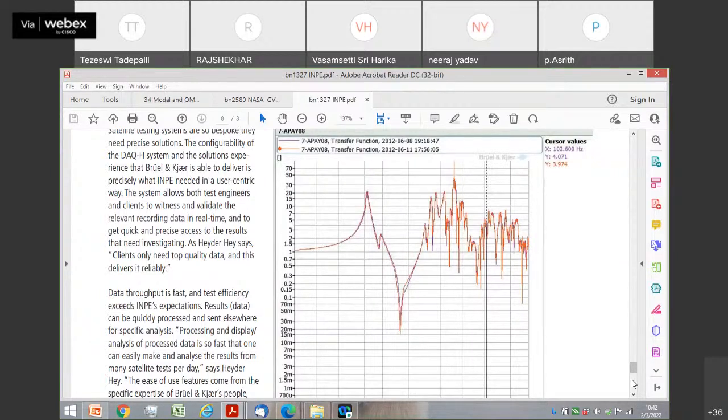Yes, in the coming test we can do that, but the same test we cannot repeat like we did on the cross country roads. So the reason is you have to have redundancy in terms of recording, so that if in one channel you have lost some data, you could look at the second channel and see whether the data is okay or not. That's the only thing that you could do to take care of such mistakes.